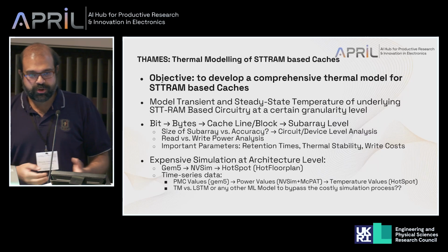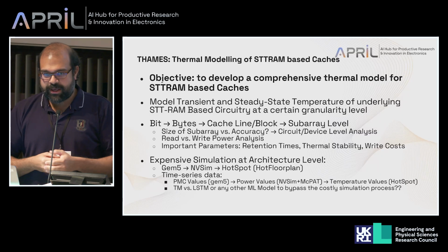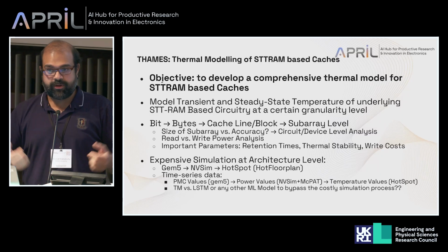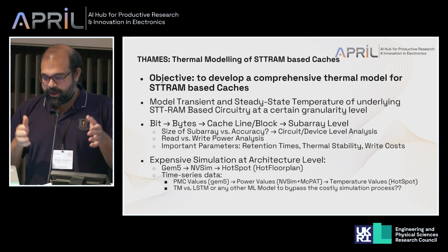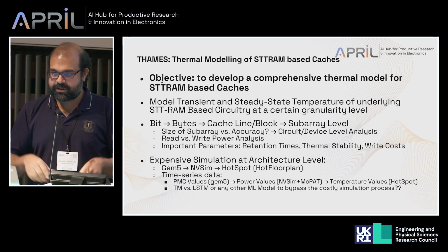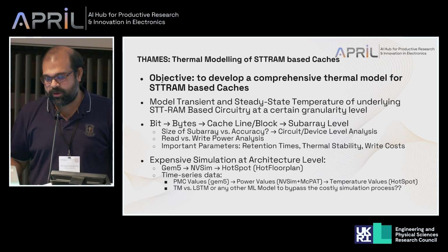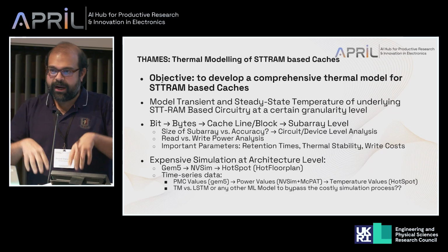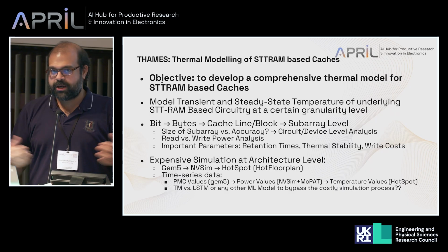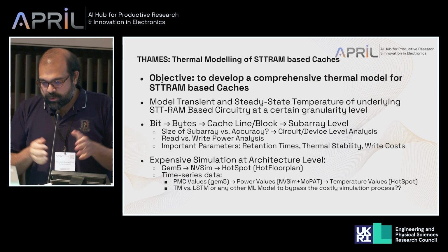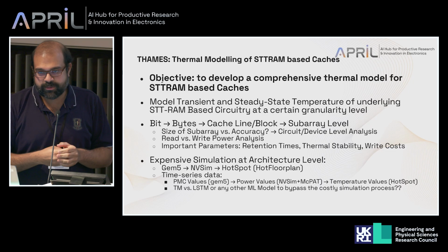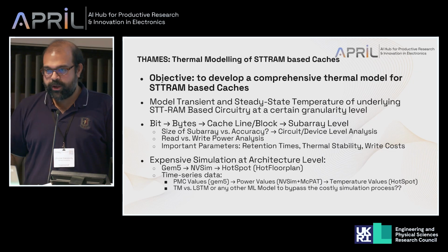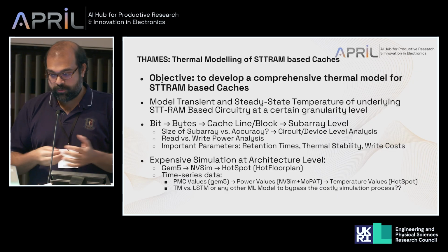Nowadays, if you just consider the last level cache, we can use 2 to 4 MB or even sometimes 64 or 32 MB of cache. So we are making the thermal precision level or thermal characteristics at sub-array levels of 2 KB or 4 KB. We can have multiple such granularities in a large LLC or large cache. Because these architectural simulations are quite expensive, sometimes it takes a week or more than that, 10 or 12 days.